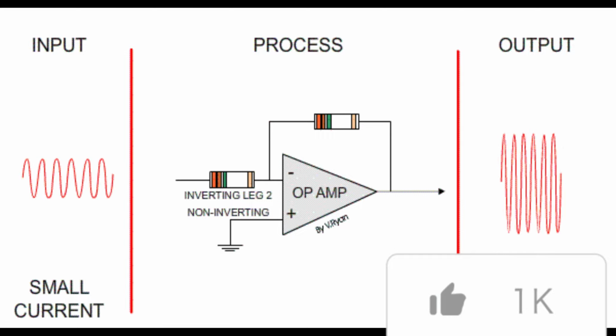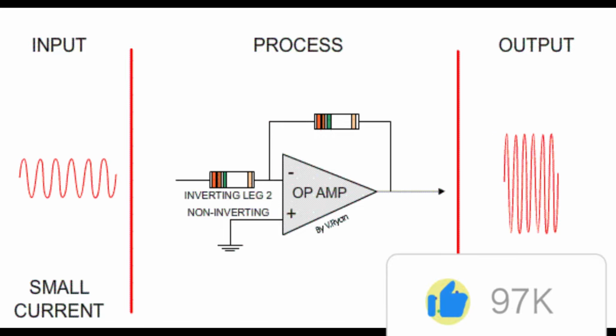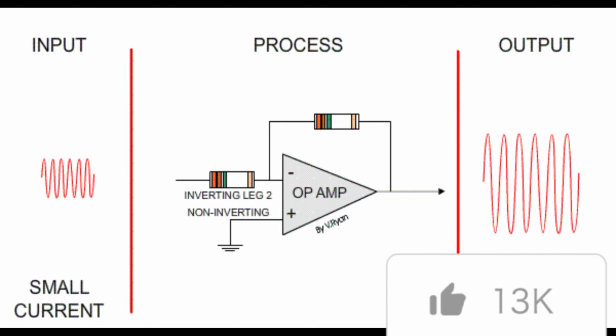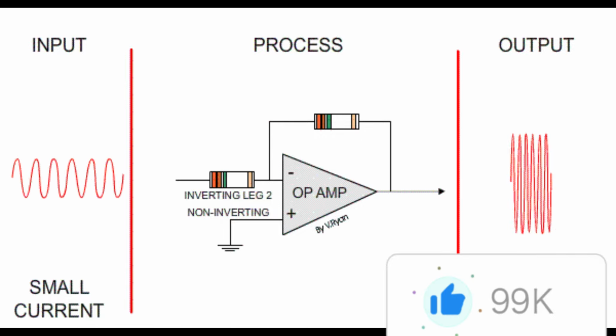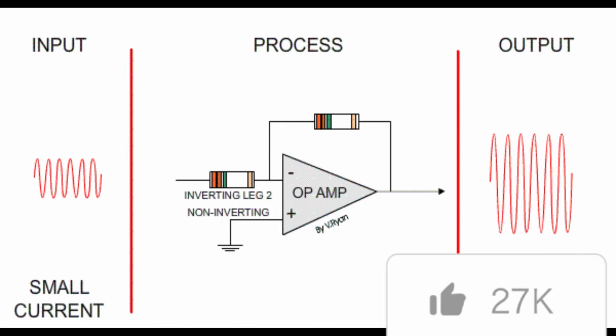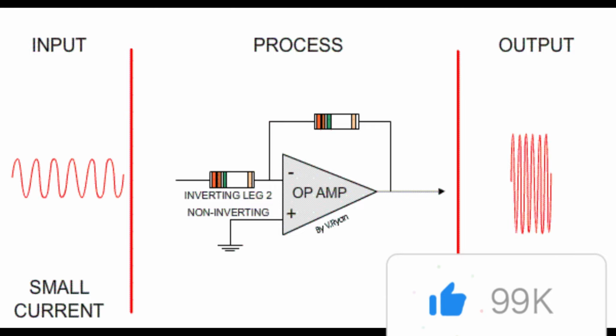Thus, a small differential input voltage must be applied to force a zero output. It is called input offset voltage and should be a small value.